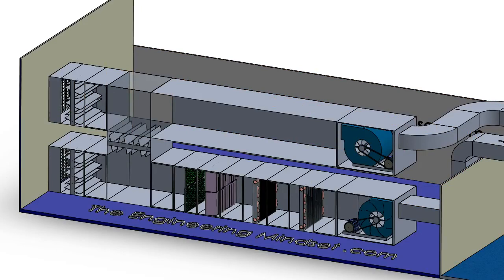And from this you can see it's a fairly typical example of a typical office supply, and that is that we've got the supply coming in. It's coming in through the grills, then past the dampers. It's got the panel filters here, then the bag filters, then it's passing through these coils. In this configuration I've done it that heating is first and then cooling. You may have it just heating, you may have it just cooling, you may have cooling before, and you might have some humidifiers, etc. in there. But this is fairly typical, at least for the UK and most of Europe.